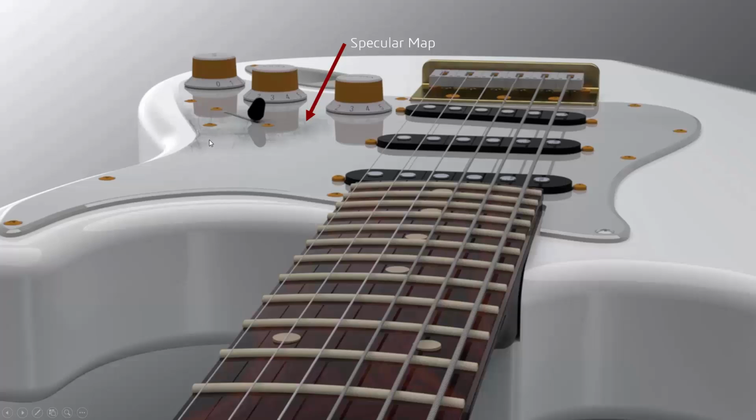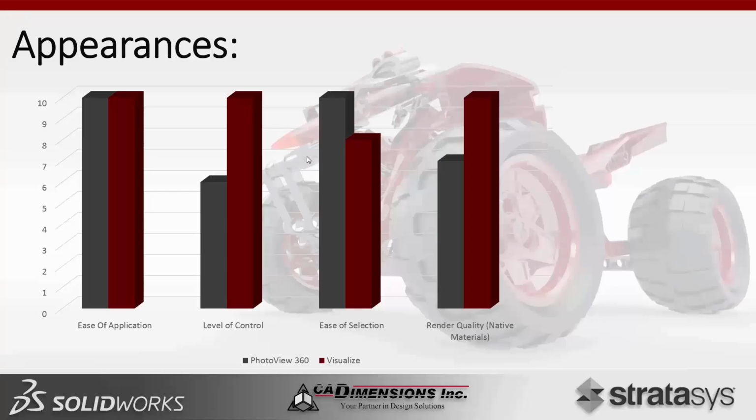So in this case, I applied a specular map in Visualize of just some scratches and some haze. What that does is, again, pull the specularity out of the appearance only in those specific regions. So it sort of gives it a worn or rough look. And again, that's available in Visualize only, but a neat resource.